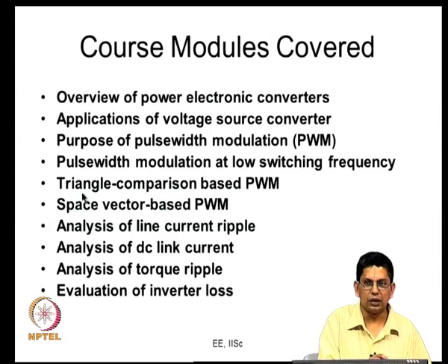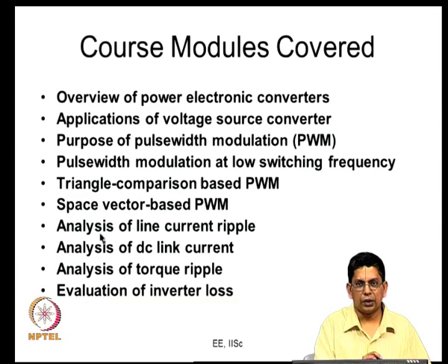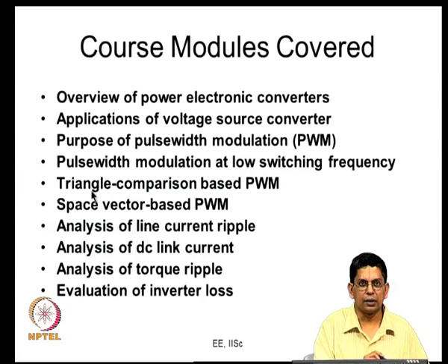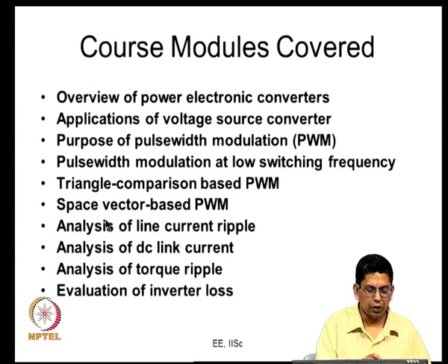The traditional method is to compare 3-phase sinusoidal modulating signals with a triangular carrier. So, instead of sinusoidal you can use several other kinds of modulating signals also, where you would have some common mode voltage, and you would compare 3-phase modulating signals against a triangular carrier. Then we also looked at the space vector based PWM.